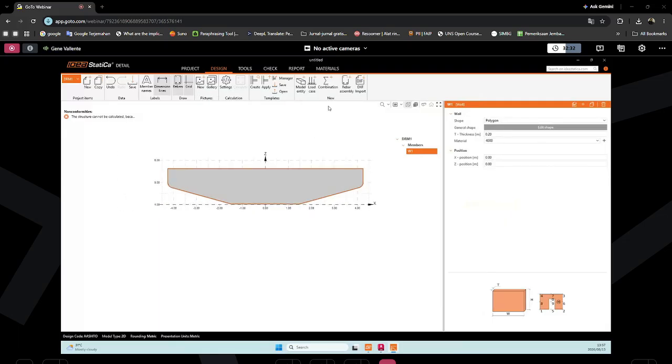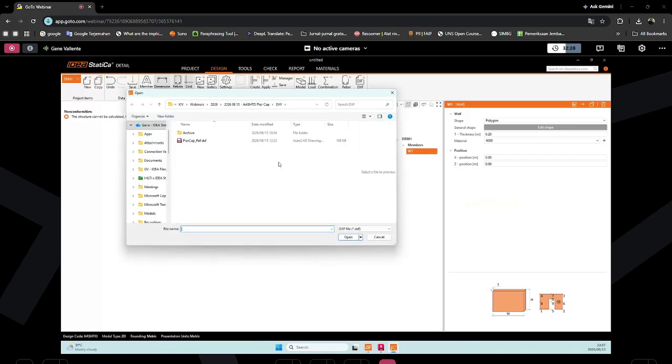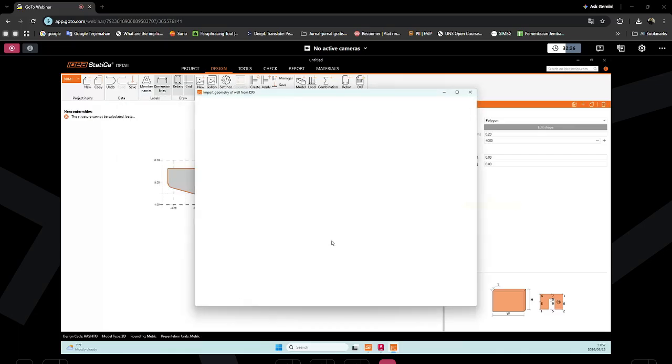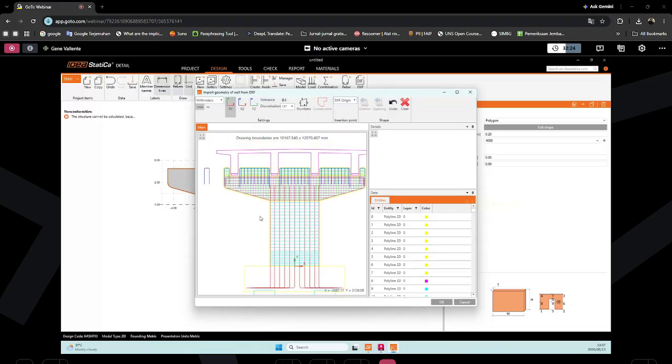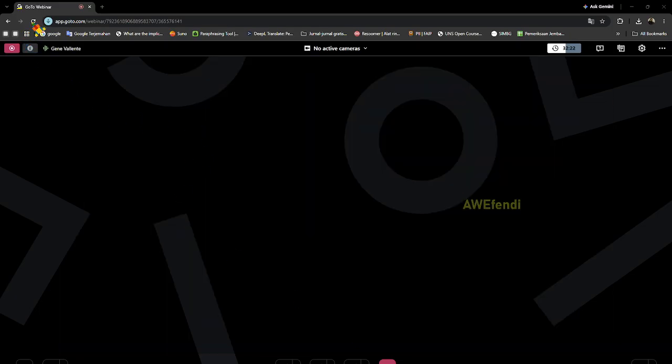You can also add another one, which is also again, and I click on member. So you can either choose a single selection like what I did here. Click on OK. But you can also select multi-selection by pressing just the control button. If you press the control button, you can basically select all the required members.